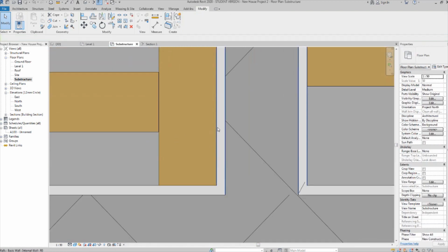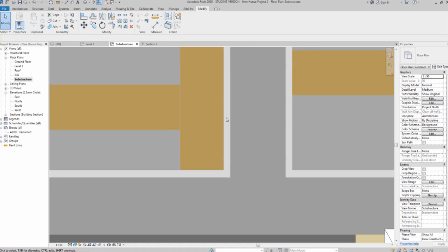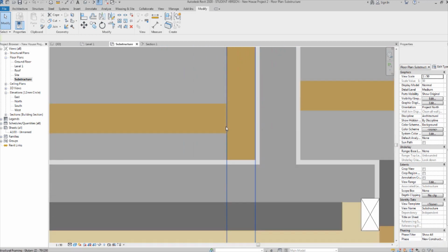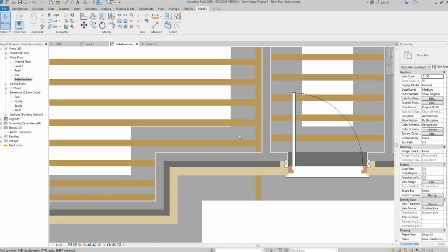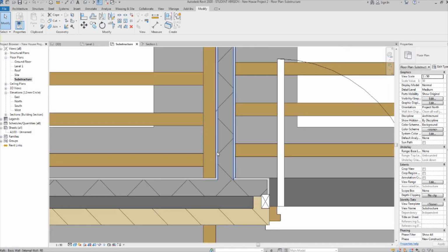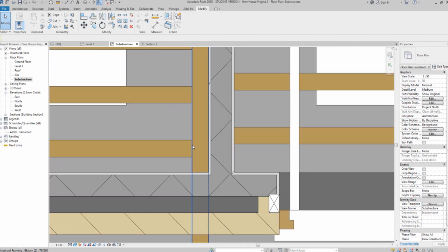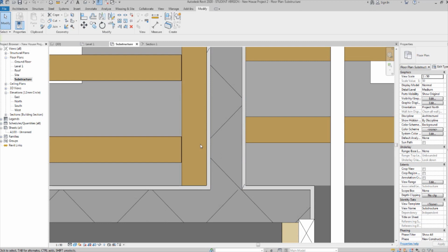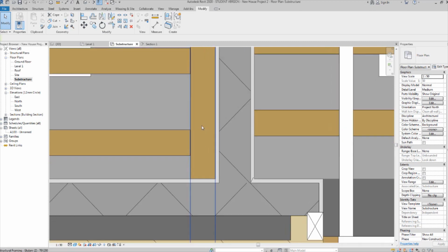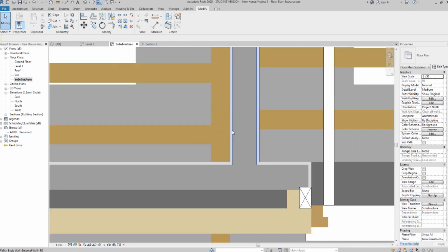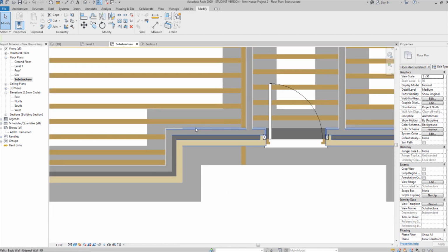In practice, you'd have a 2 mm tolerance gap between the joists and the wall, so they can fit it in a little bit easy without it sticking. If they were dropping it in with a crane, and it was exactly as the dimensions are for this room, then it wouldn't go down so easily unless everything was perfect. So the 2mm tolerance gap is there to allow it to sit in place.